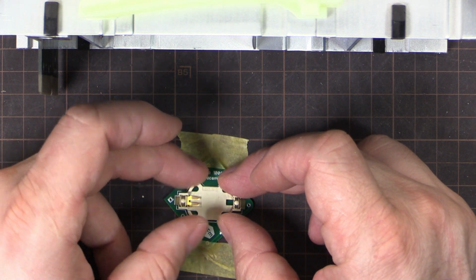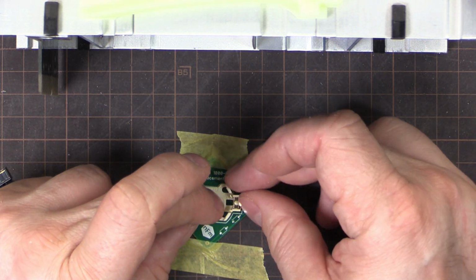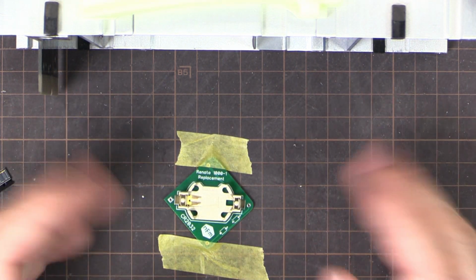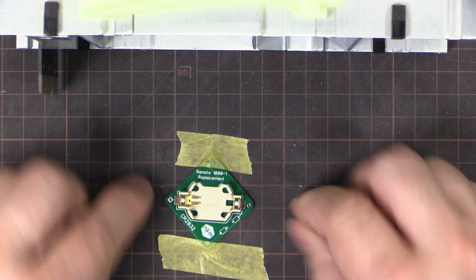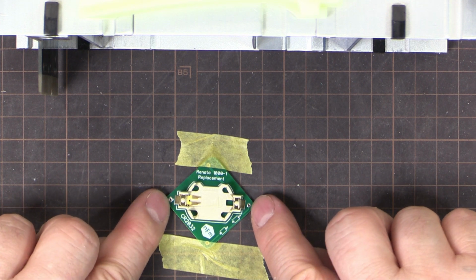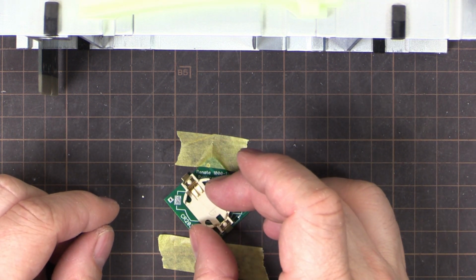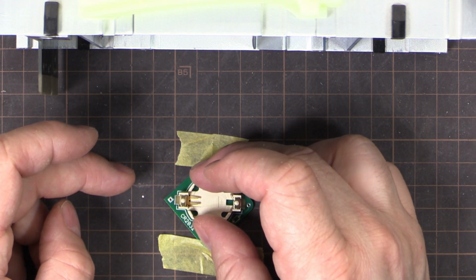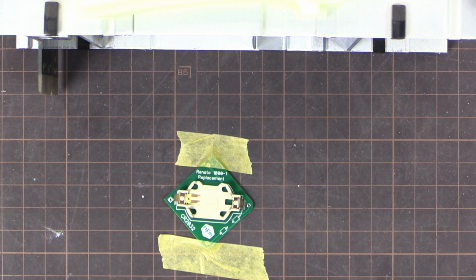Oh, my footprint fits. Sweet. I had to cheat on the width of the footprint so I wasn't going to get too close to the pins here. It's also why it's sideways, at a 45-degree angle, because otherwise it's too big. But that is pretty good.